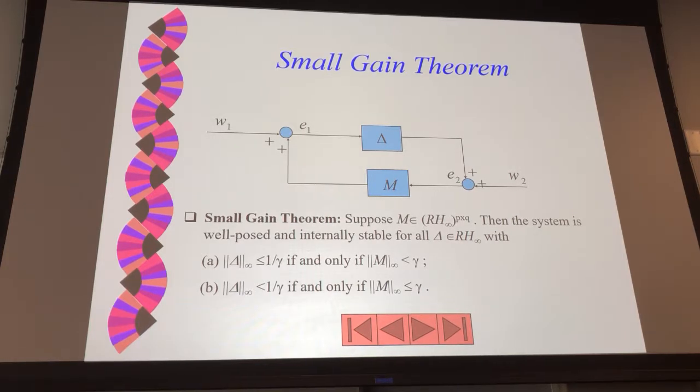What you should do then, just stabilize it first. Okay? Using a simple stabilizing controller to stabilize first. Then you improve the control performance or stability margins using other methods. So open loop unstable systems no longer satisfy this RH infinity. Okay. Again, let me repeat what RH infinity is. Last time I may have said it wrong. It's just proper stable transfer function matrices.